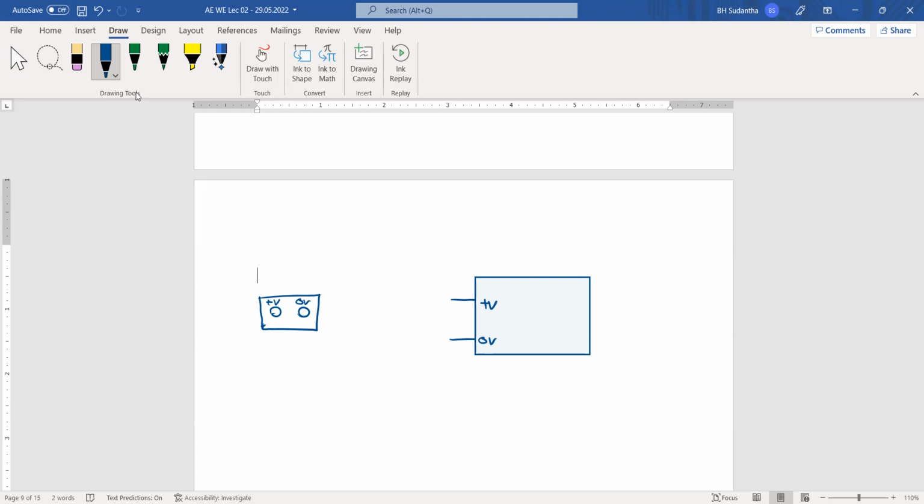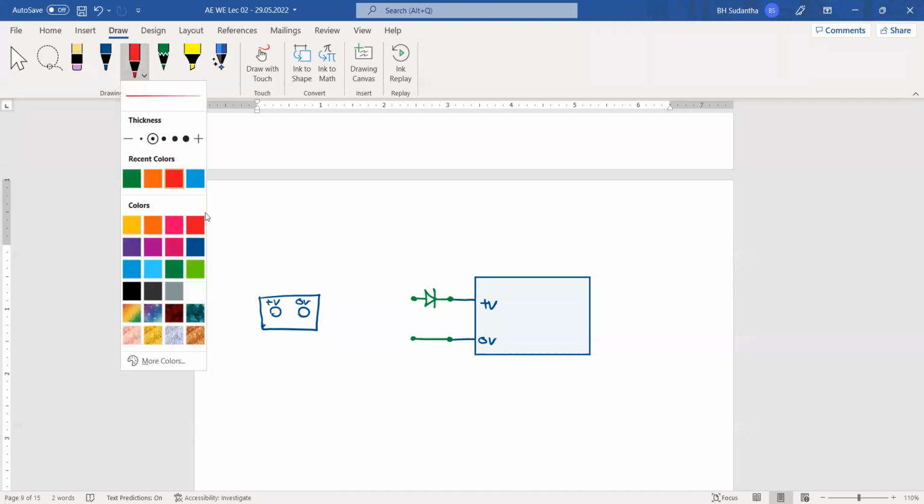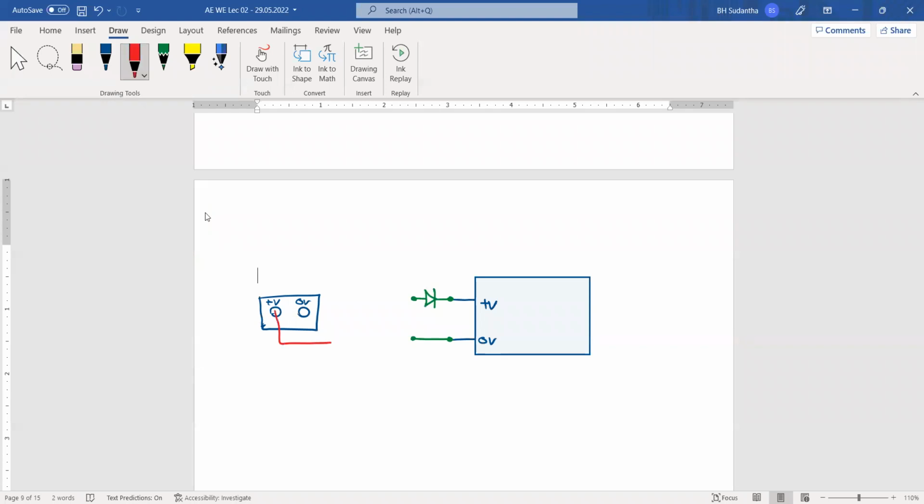And you can include a diode here, in front of your circuit. Then after that, these are the new input points to your electronic circuit. Now you can provide these connections to the supply like this, and there is no harm to the circuit.